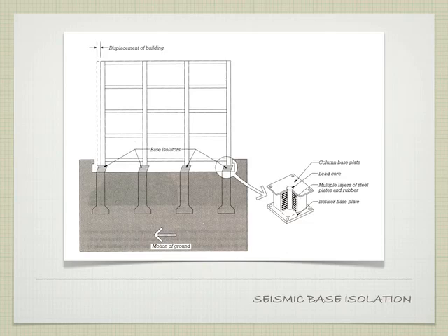And then on top of this foundation, they put these seismic base isolators, okay? And basically the concept here is you have a plate at the bottom, right? You have a sandwiched layer of steel and rubber, right, that run in between, right, here and here. Then we end up with a top base plate that attaches to the building, right? Or attaches to the former foundation of the building, depending on how you generate this.